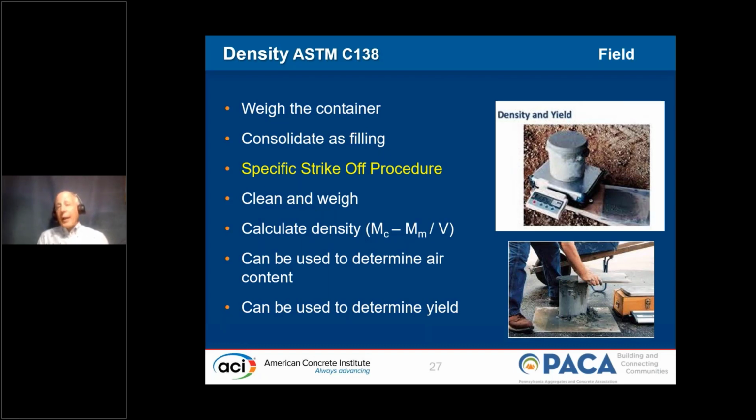And I like to use this very often because if I have a pressure meter reading that doesn't go along with the dosage of air entraining I'm putting in, or seems kind of odd, the best way I feel to check it is to run the density test and check my air content gravimetrically. It really can be an important step before I change something on the mix, when I want to really know I'm measuring the air properly.